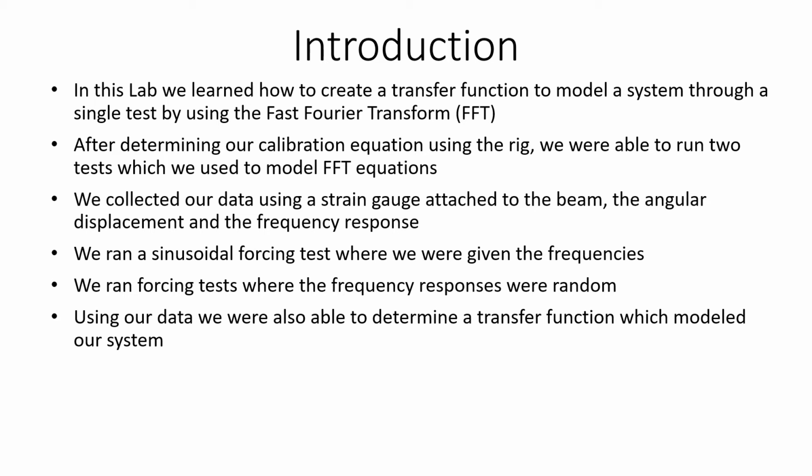For our random forcing test, we found that our graph for the FFT had a smoother curve due to the larger amount of input frequency responses. However, it was not as accurate in predicting the system response as our sinusoidal forcing tests.